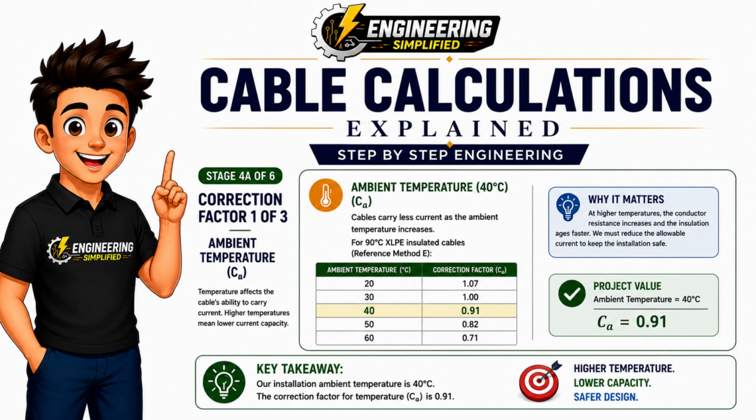Let's begin with ambient temperature. Our installation has an ambient temperature of 40 degrees Celsius. As the surrounding temperature increases, the cable becomes less effective at dissipating heat. This means the conductor operates at a higher temperature, and the amount of current it can safely carry must be reduced. Looking at the correction factor table for 90-degree XLPE insulated cables, we find that an ambient temperature of 40 degrees gives us a correction factor of 0.91. This tells us that the cable can carry only 91% of its published current rating under these conditions.